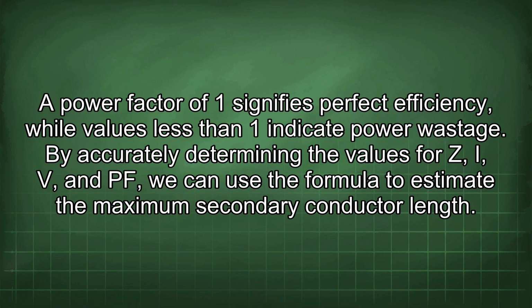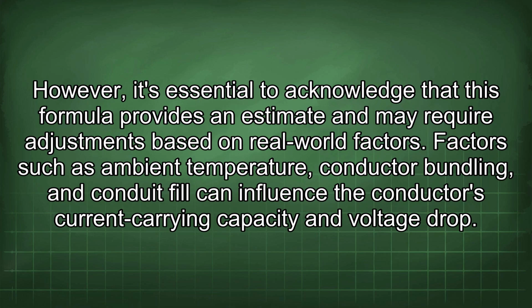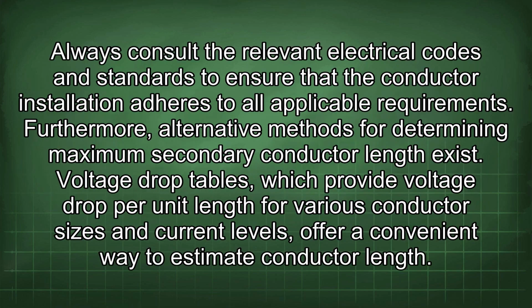secondary conductor length. However, it's essential to acknowledge that this formula provides an estimate and may require adjustments based on real-world factors. Factors such as ambient temperature, conductor bundling, and conduit fill can influence the conductor's current carrying capacity and voltage drop. Always consult the relevant electrical codes and standards to ensure that the conductor installation adheres to all applicable requirements.